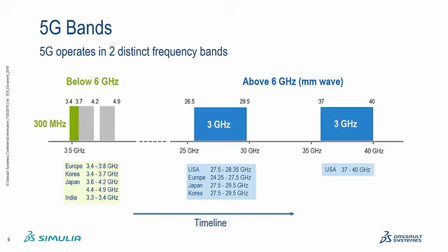One disadvantage of the millimeter wave technology is it's really limited to line of sight, and it's easily blocked by, for example, the human body or the human hand. That line of sight issue can in fact be exploited through reflections off buildings, for example, in what's called a multipath effect. But fundamentally, 5G products are going to need two systems added to the device. So this is an extra level of complexity. Millimeter wave also brings new challenges around casing design, material selection, and so on.